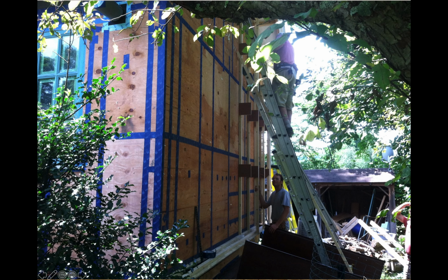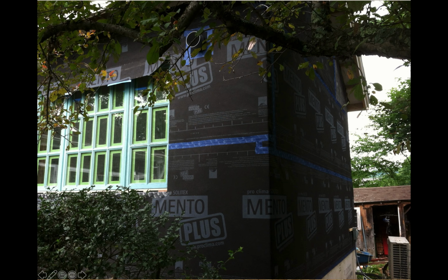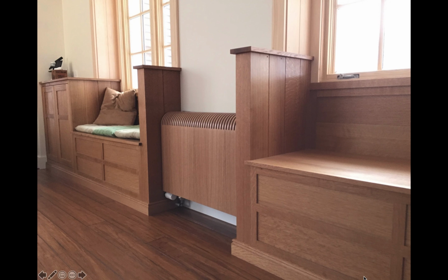And then on top of that existing plywood sheathing, which we taped as our air barrier, we started to add what's called a Larson truss. So we built out the insulation towards the outside, and then we put a membrane on top of that. So there is no exterior sheathing, which certainly at this time was unusual, at least in the United States, for typical framed buildings.